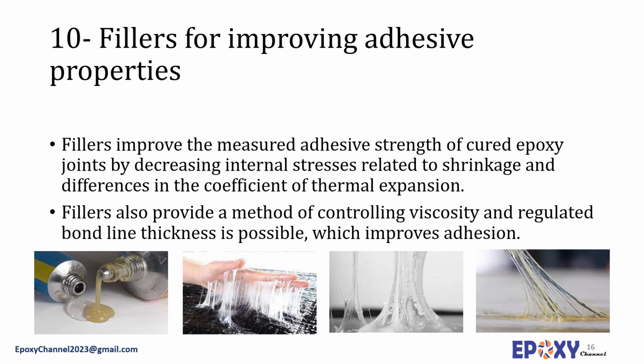Fillers have very little effect on the actual adhesion mechanism, since most of this is controlled by intimate contact of the liquid epoxy and the substrate. However, fillers improve the measured adhesive strength of cured epoxy joints by decreasing internal stresses related to shrinkage and differences in the coefficient of thermal expansion. That's why a significant improvement in tensile shear strain with the addition of fillers can often be seen.